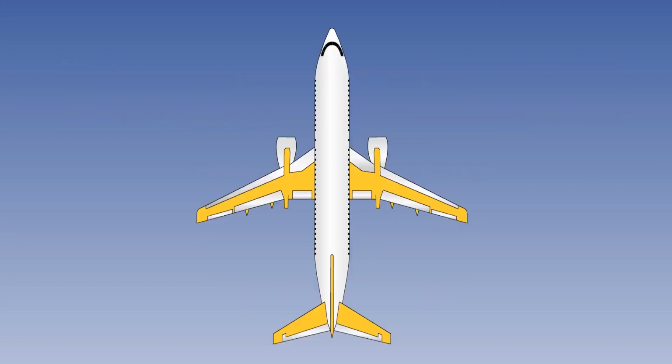From the factors just discussed, and particularly the last, aspect ratio, it can be seen that a high aspect ratio, that is, a fairly long, narrow wing, is preferable for aircraft designed to operate at around Mach 0.8 for the greatest part of their flights, as are conventional high-speed jet transport aircraft. This is because of the relationship between induced drag, lift coefficient, both low at high speeds, and aspect ratio, expressed in the formula CDI equals CL squared over AR. The higher the aspect ratio, the lower the induced drag.